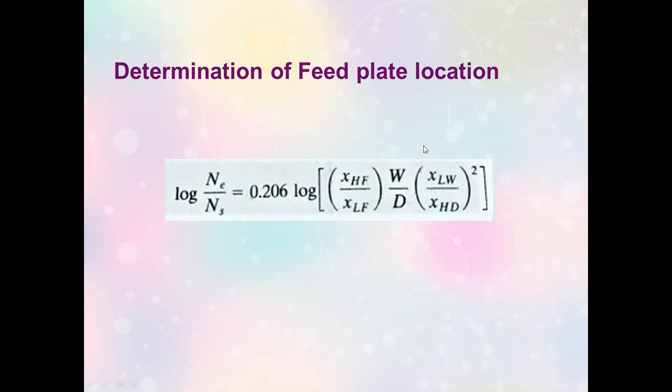If it was shown to you graphically that the upper portion is enriching, the stripping section is stripping, and in between is the feed plate, then it follows that on the upper part, you have the enriching section. Next to that right away will be the feed plate, which is part of your stripping section. So very good, Kenneth. Your feed plate is in the 11th plate of your column.